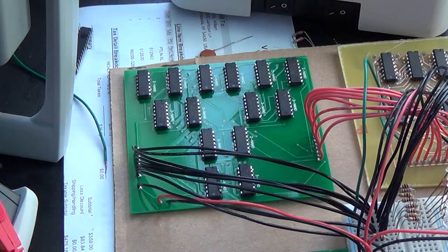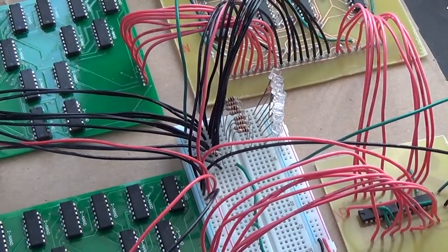So each time I pulse the enable of the A register high, the A register will accept the previous sum, and a new sum, which is 1 greater, will appear in the LEDs.